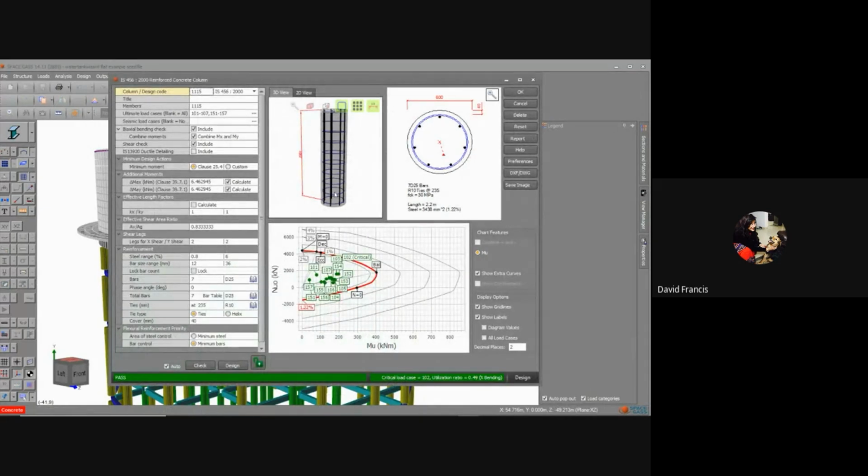So there is the conversation I had earlier when I wanted to change the staging. I couldn't get the column to pass the design because it was too small, because there were 26 columns instead of 31 columns. So there is rerunning the analysis, playing with different configurations, and then coming to get your design here.